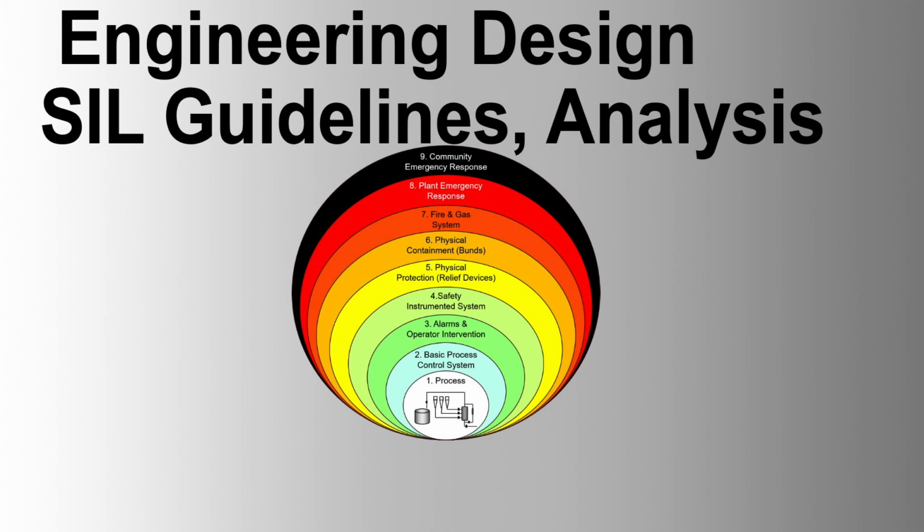Assumptions for fault tree calculations for an SIS. Several key assumptions are made when using FTA for SIS evaluations. The SIS is designed, installed, and maintained per ANSI ISA S84.1-1996. Component failure rates are constant over the system's life. Component failures are statistically independent, although dependent failures can be modeled. Once failed, a component remains in that state until repaired. Testing is assumed to be perfect, detecting all covert failures. Repairs restore components to their normal state, with imperfect maintenance considered for higher SIL applications. Testing frequencies are higher than failure rates. The reader is familiar with FTA techniques and principles.